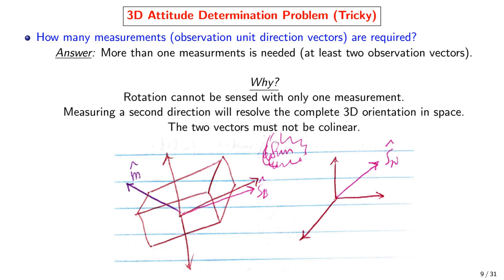I thought someone is going to say we need 2. We cannot actually know if we need exactly 2, but we can be sure we need at least 2 measurements for a 3-dimensional space. And that's because you need to consider your rotation, which cannot be sensed with only 1D, with only your resultant force.